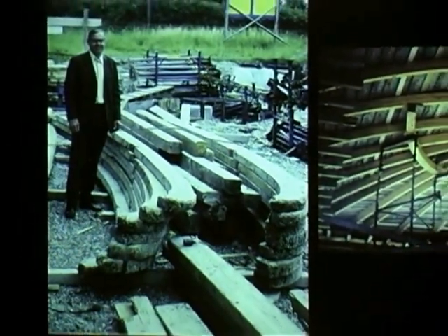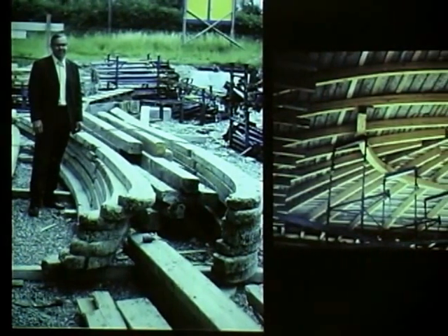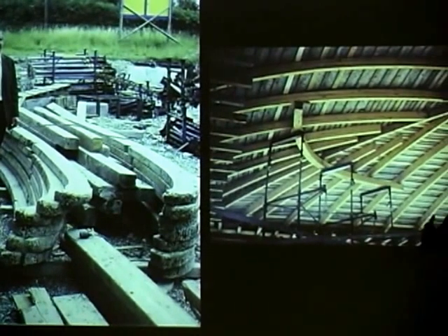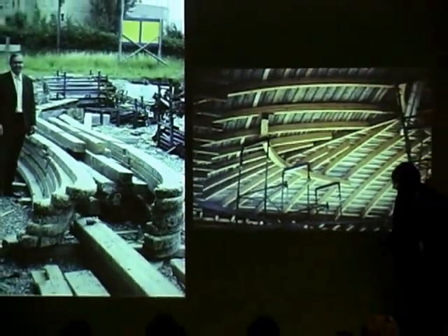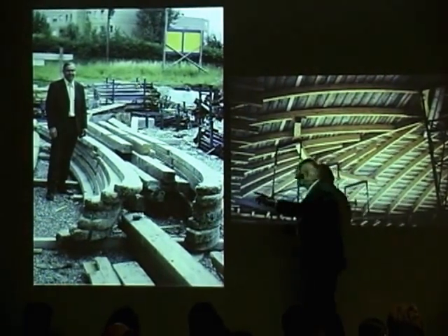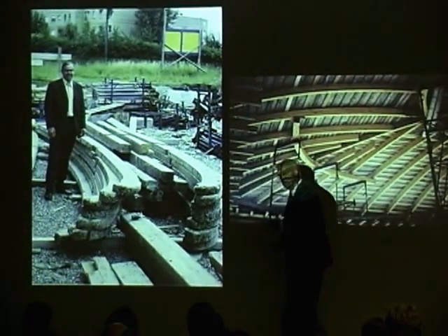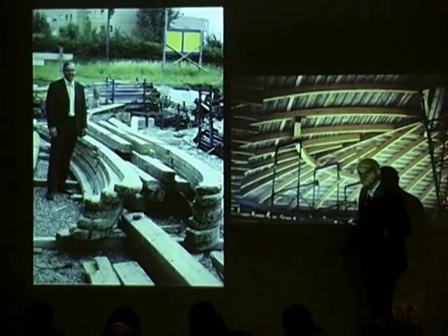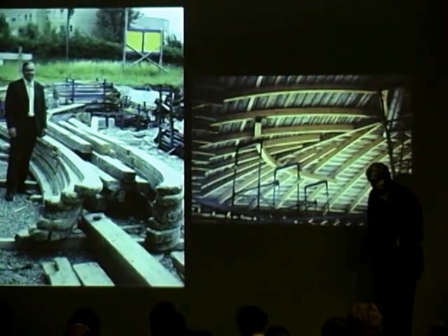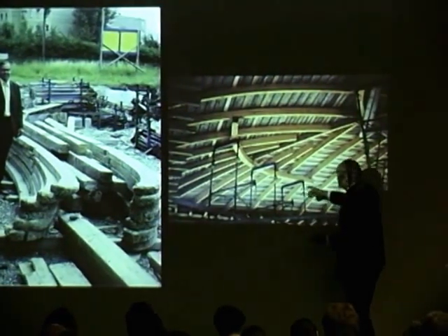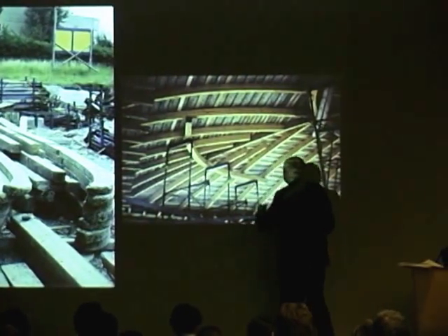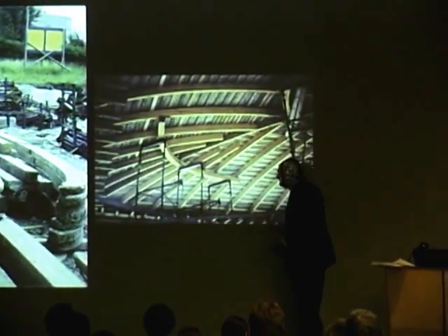And he's building these thin shell roofs, where the major expense is the formwork that holds them up before the concrete is hard enough to take away. And so what Easler is doing is using very expensive laminated wooden arches, but designing in such a way that he can keep reusing them many, many times. So the cost on any project is very low, even for these expensive ones. So he puts these up, here you see them, and he has a light metal scaffolding. And then on top of that are slats that are just battered in place.